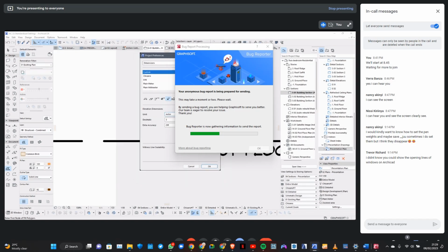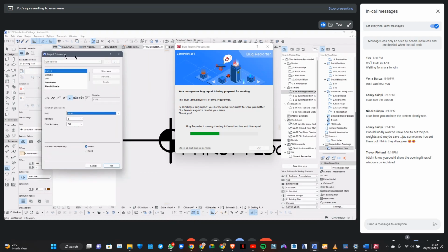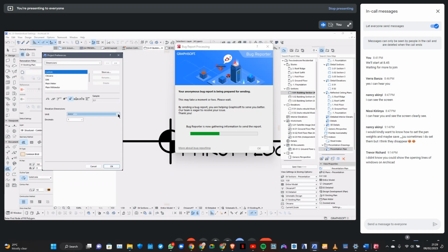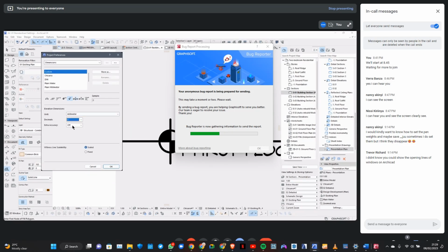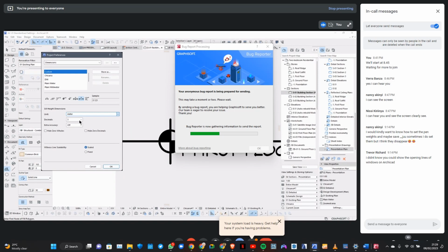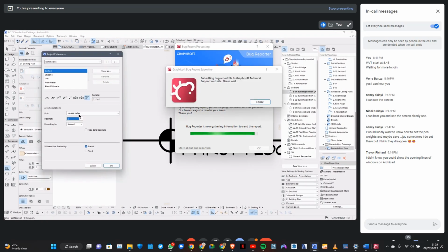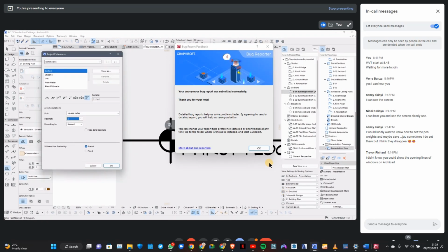Elevation units. So elevation units are like these ones here. This in elevation, that's an elevation unit, elevation dimension. So same thing. If I dive to the dimensions for the window and skylight, yeah, so as I continue to build this, that's my dimensioning preference. That's how I want ArchiCAD to be showing my dimensions. And finally, on square meter, it's much easier to work with square meters to 2 decimal places.